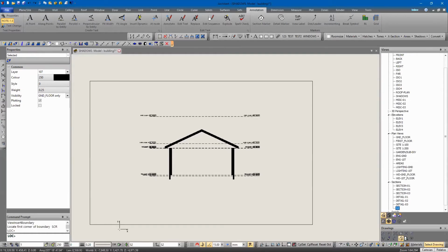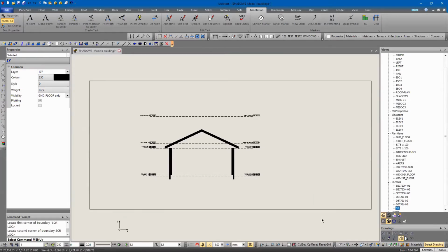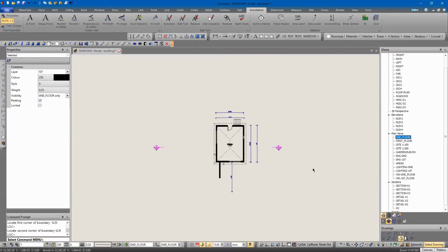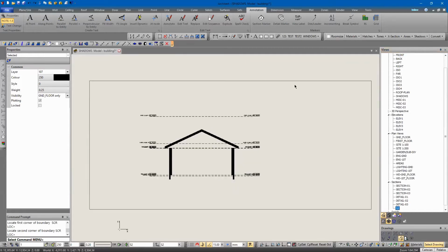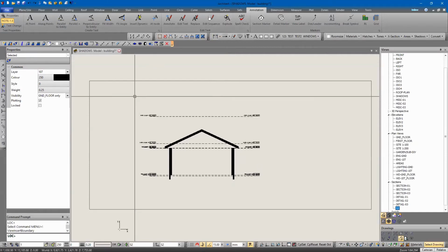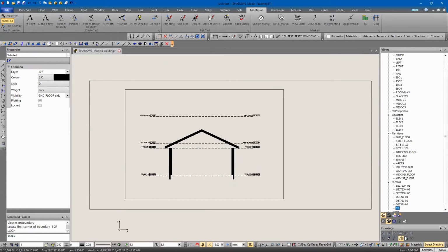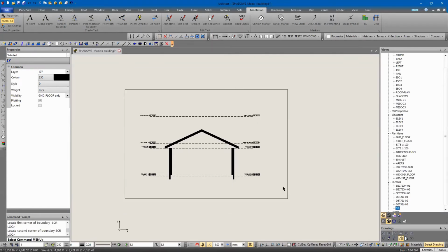They'll only adjust if you put a new plot boundary back in, and see they've disappeared way over here. So just bearing that in mind, if you want an extensive amount of extra notes, you'd probably stick that into a separate view and keep your plot boundary in a place which makes sense to the positioning of the markers on the drawing.